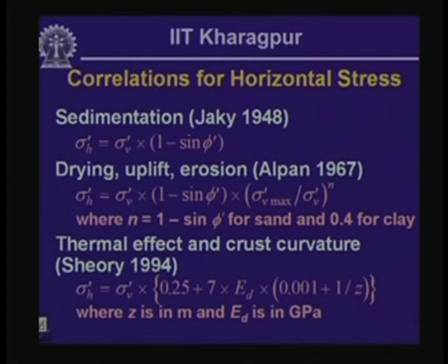Now, if you have got unlithified sediments, freshly deposited unlithified sediments that have consolidated or stabilized under their own weight, in that case sigma h prime is going to be equal to sigma v prime multiplied by 1 minus sin phi prime, and this is the expression proposed originally by Jaky, and it actually works quite well in case of unlithified soils that are yet to get cemented and become rock like.